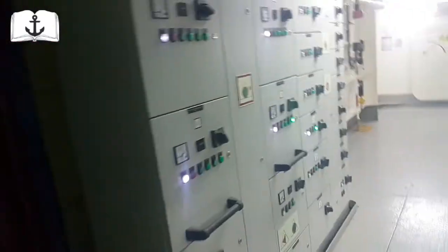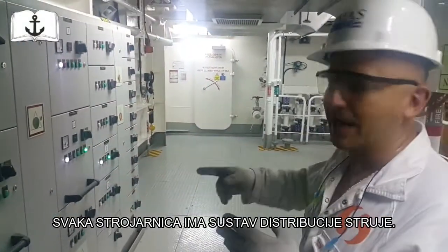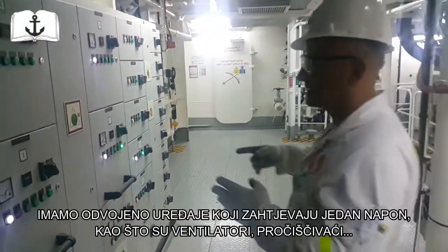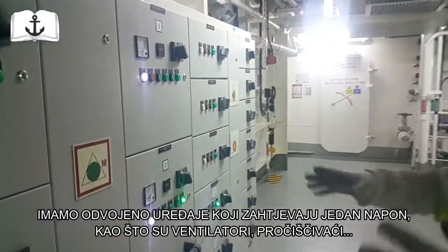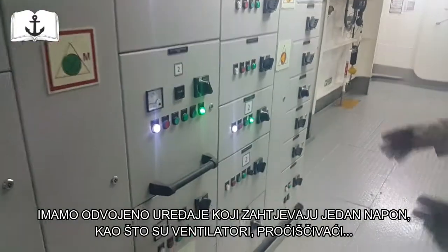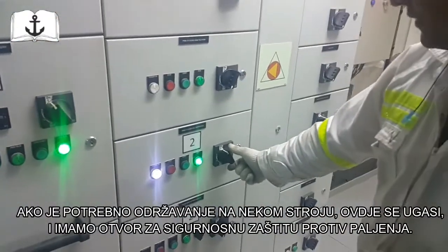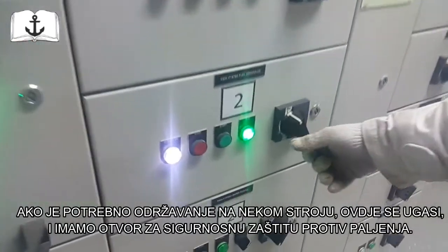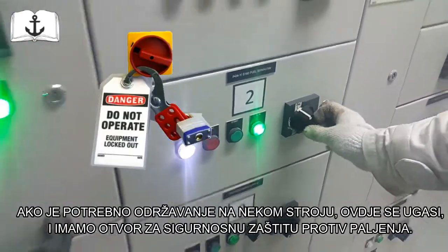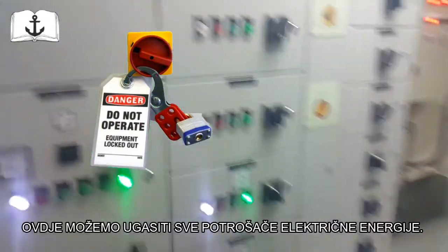And in every engine room, you also have the distribution board. It's the 480 equipment. So for example, we have the power here for the fans, we have the power for the purifier, for the compressor. If you're doing any maintenance, you should shut off the power, then you put the padlock. Here is the place for the padlock, you're making isolation. So over here you can turn off all the machinery.